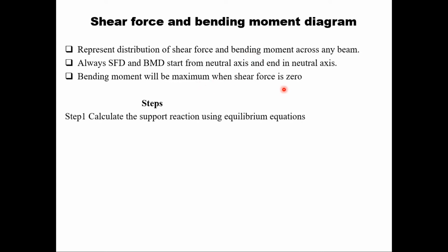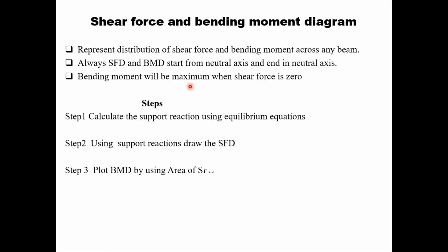So what are the necessary steps to construct shear force and bending moment diagram? So first we have to calculate the support reactions using equilibrium equations. Then we will use the support reactions to draw shear force diagram. Finally, we will plot bending moment diagram by using area method. So area of shear force diagram will give us bending moment diagram.